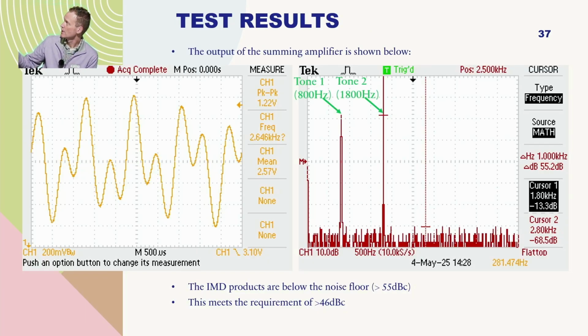So you can see a strange waveform, but that is what two tones added together looks like, unmodulated. This is still audio frequencies. About 1.22 volts, and the oscilloscope's completely confused because I've got two audio frequencies. You can't work out what frequency it is, so don't worry about that. It's pretty meaningless.